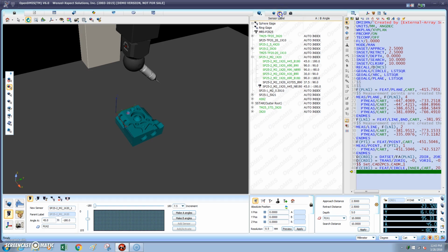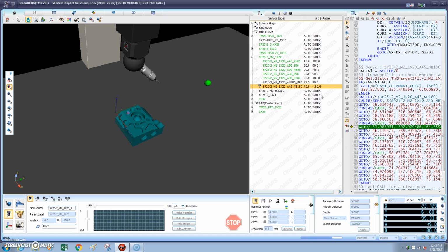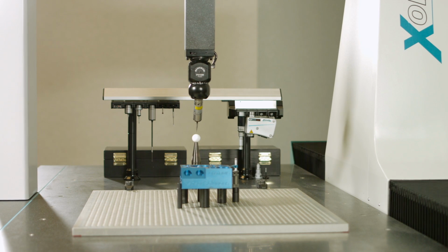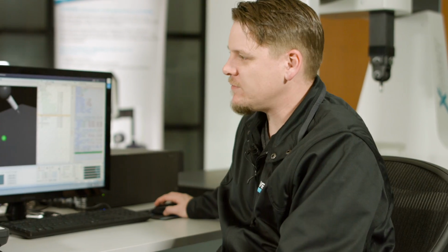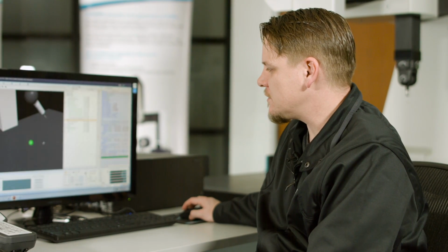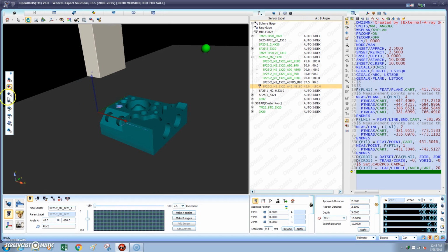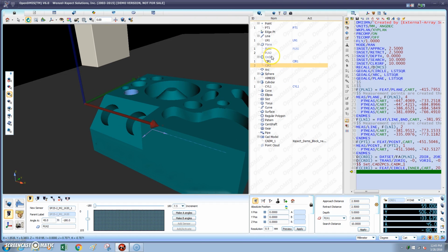And from here it's very easy to calibrate. If I go here to my sensor database, I can then select this to then be calibrated against my reference sphere. So after I've calibrated that sensor, I can then use that sensor to then measure. So here if we select it again off the CAD file, I can then program in a scan path against it.